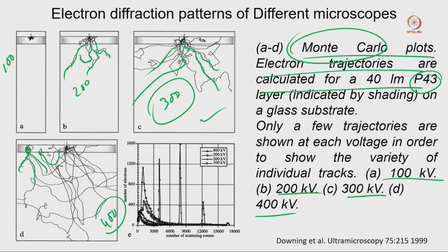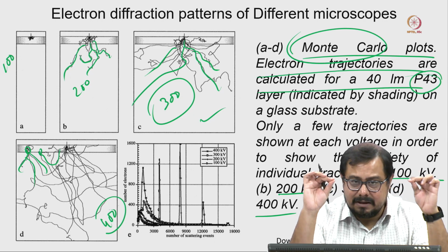Also, readout is very slow, and that is one of the reasons we can consider that it will always give us an integrated image. For any kind of imaging we need some kind of exposure, and this exposure time is very important. So, if exposure time is something like 4 second, 5 second, 8 second, what will happen is it will just give us one integrated image. It cannot give separate images. A 4 second exposure it will take and one single image it will give.